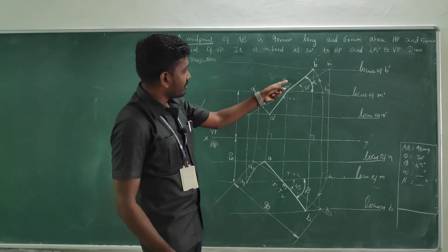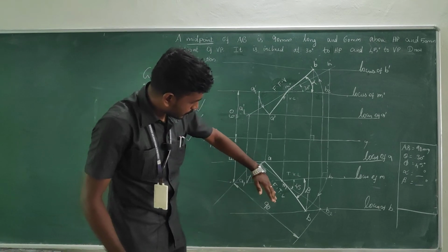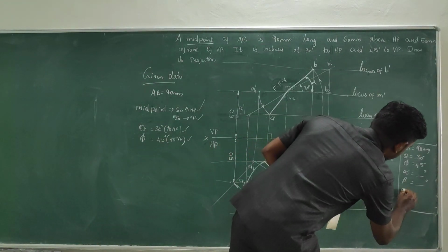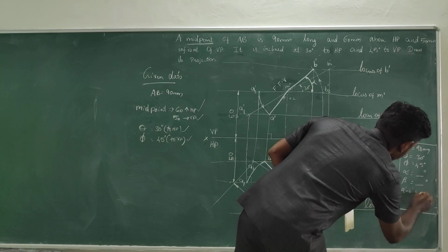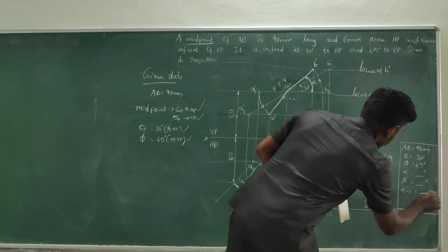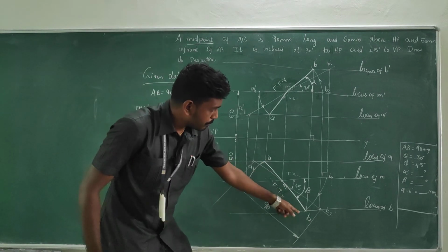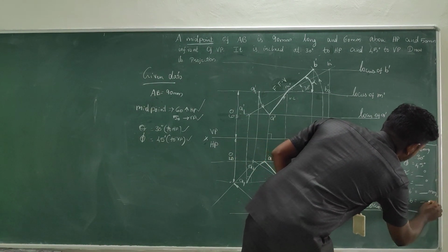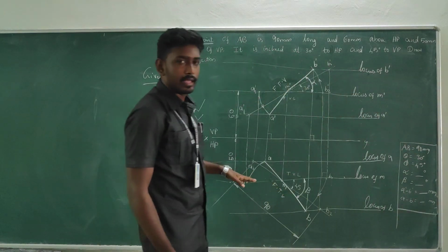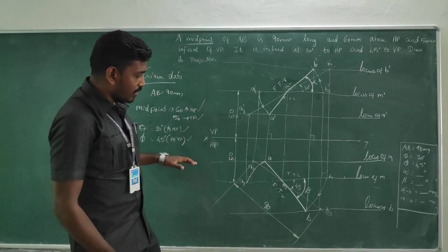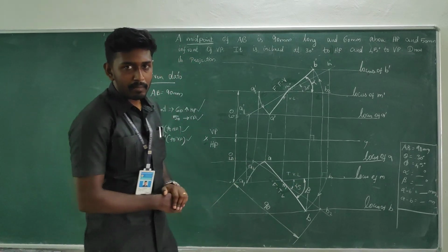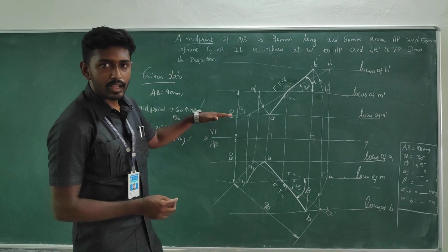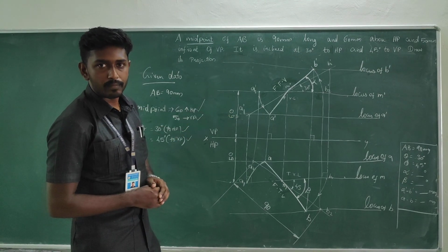Okay, and the final front view length, as well as the final top view length, we have to measure. You measure from A dash to B dash, we get the final front view length in mm. Now if you measure A to B, we get it in mm, which is the top view length. Okay. Afterwards, capture the note. All dimensions are in mm. As well, we can provide the scale. Okay. Here we have used the true scale, so mention it as 1:1. Thank you so much.